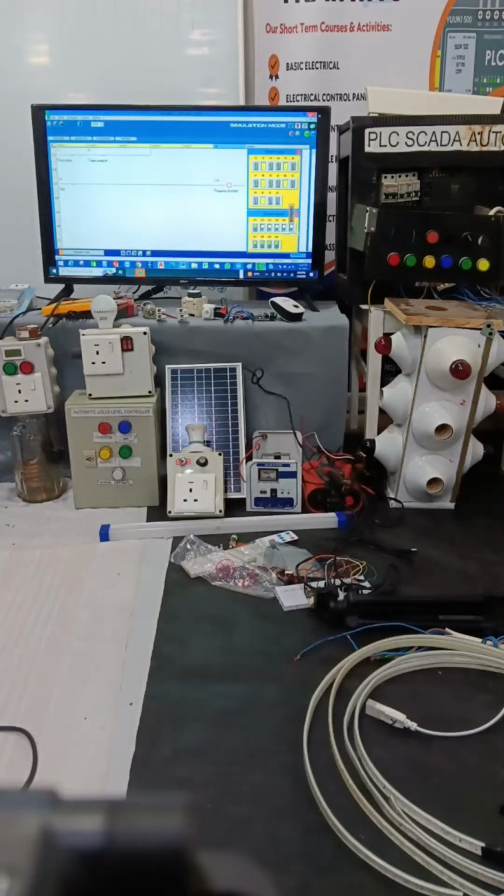Now suppose some inductive loads are switched off, like a blower or pump or lift or escalator. Then for power factor improvement, you need to reduce your capacitors, one switch off. So the controller switches off one contactor, and this contactor will open.